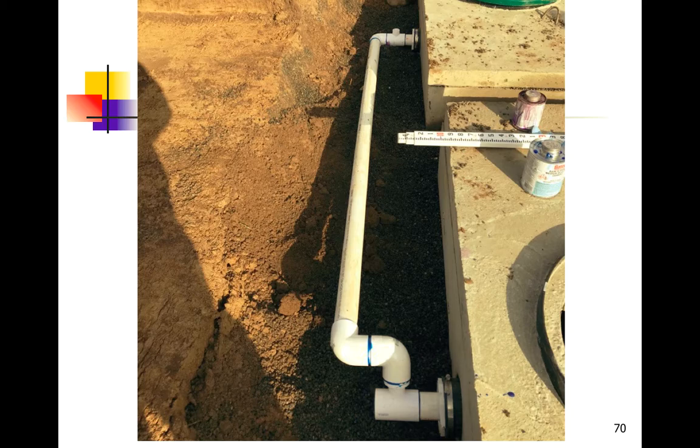So here in this illustration, we can see the tank adapter for the 1,500-gallon tank is closest to us. The best way to do this is go ahead and put your laser level story pole on top of that 2-inch pipe as it comes out of the tank. Get yourself a reading, and then you're going to want to dig a shelf, illustrated here on the left side, that's 2 inches higher in elevation in the soil than that 2-inch stub.